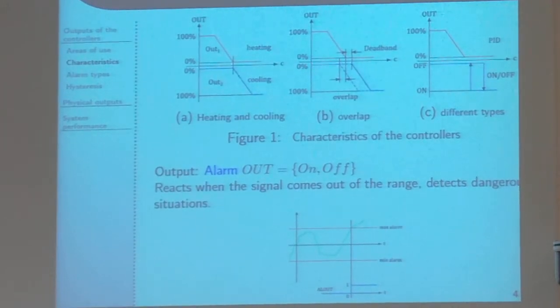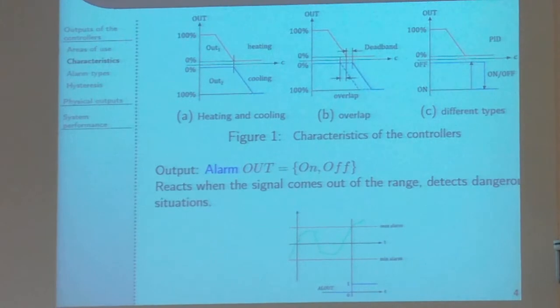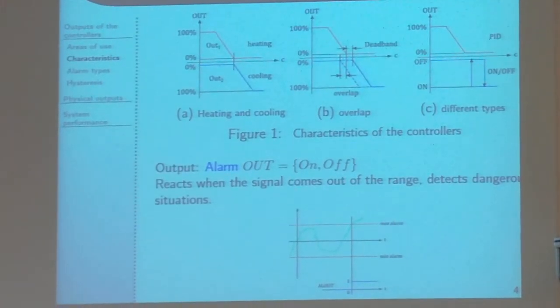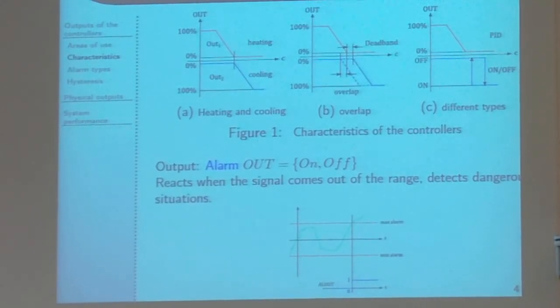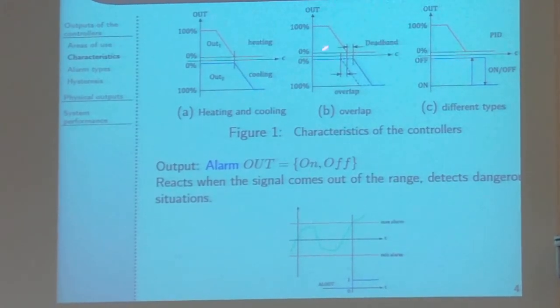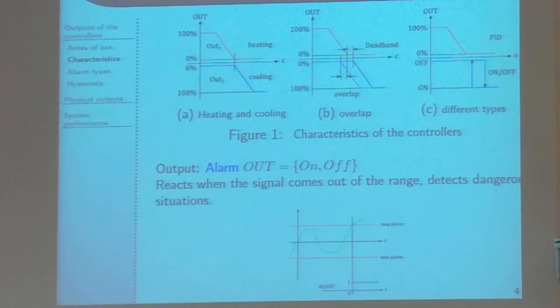The rotation of the motor was, for example, clockwise, and after that we need to change the direction of the rotation. And if the deadband is too small, we can break our motor. So for that matter, it is better to have some deadband between those characteristics.